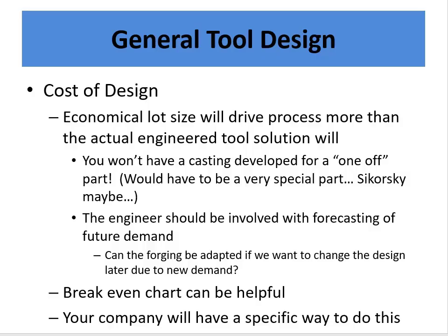So if you're going to come up with some near net shape process, casting or MIMing or something along those lines, you're probably going to need to make enough to make it worth your while, because you're going to have a lot invested into tooling.